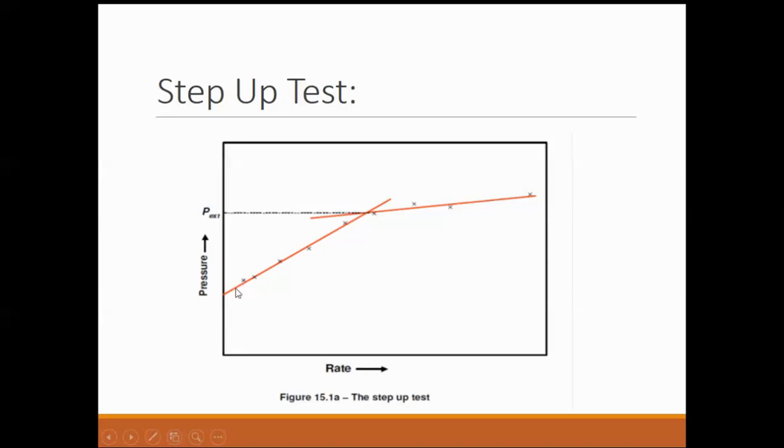Okay, sorry, this red line is the measured surface pressure. The red line is the actual pressure that you recorded during the frac job. And the blue line is the surface pressure, a curve that has been fitted to this actual curve. So all the parameters are analyzed while you feed this data into software. This particular output has been given by a software called Frac, and it is generally used by Baker Hughes.